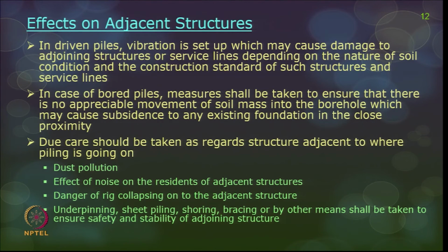When you are doing bore piles, measures should be taken to ensure that there is no appreciable movement of soil mass into the bore hole, which may also cause subsidence to any existing foundation which is in the very close vicinity of the pile which is driven.